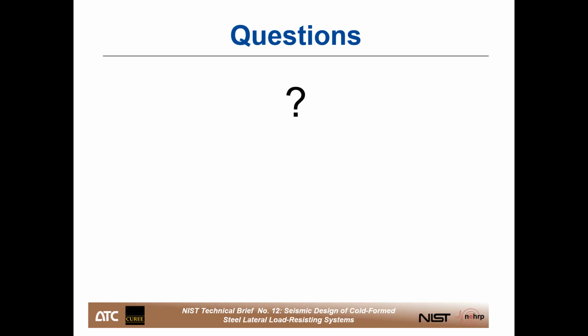Can we use the same R and omega factor for CFS on podium slabs? Yeah, that's another simple question with a complicated answer. I believe that you can. There's been some changes in the codes, and I am not necessarily an expert on exactly where in ASCE 7 those mixed systems are addressed. It's my understanding that there are provisions that say podium type structures can be designed where basically once you get above the podium, you pretend that the entire structure was always cold form steel when you choose your R, your CD, and your omega naught.